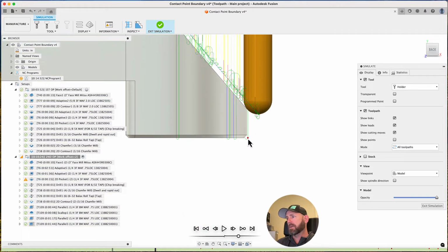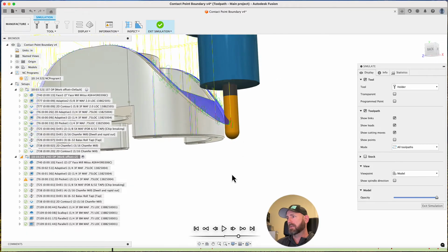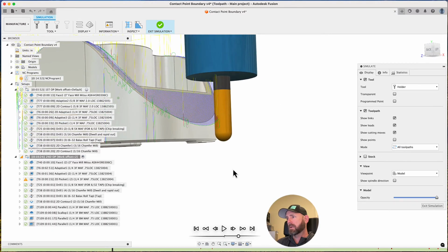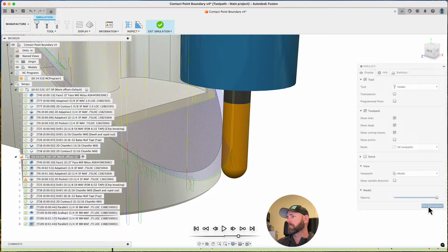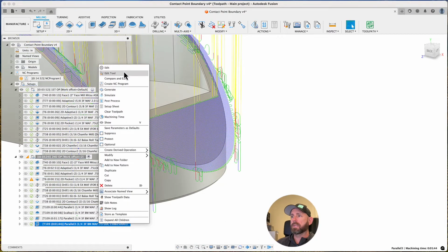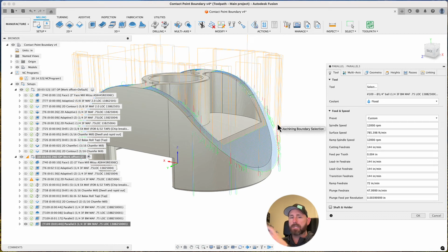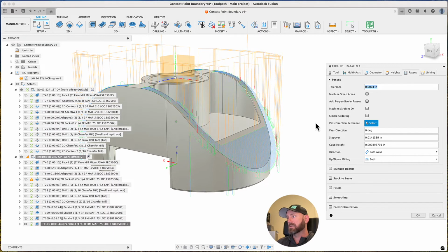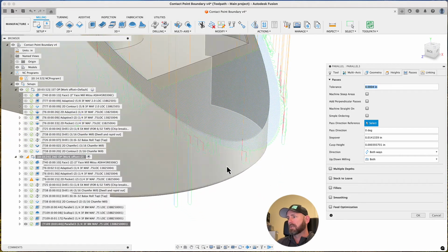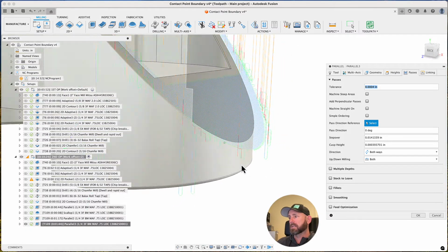Now let's understand this waterfall. What the heck is happening with this waterfall? The answer lies in the toolpath tolerance. So let's go take a look at that. As I mentioned before, in the background, there's a tessellated model that's created at the tolerance of the toolpath tolerance. So there's a bunch of little triangles created, and at a 4/10,000ths toolpath tolerance, there's some little triangles down here that it's finding and it's saying, hey, I can use the whole contact point of the tool to go cut that geometry. This is exactly what it's doing here.